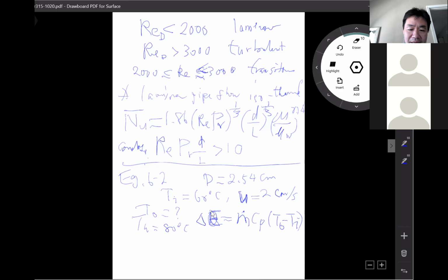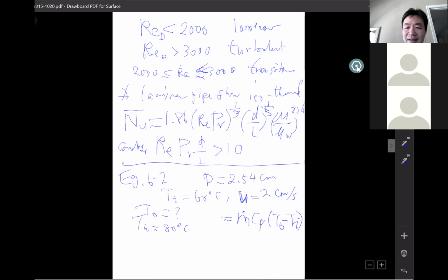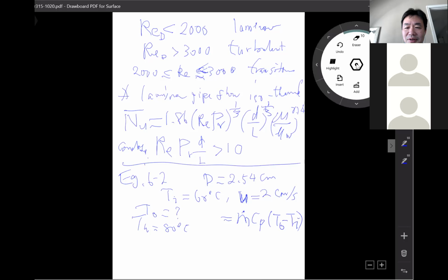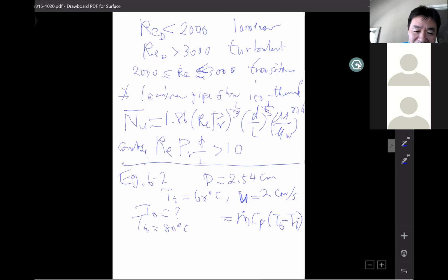So then in our heat transfer, we can replace this delta E by what? Q. Yeah, by Q. You're good now. Okay, energy balance, right? That's the total energy gain. It's our total heat transfer into the fluid from the pipe.